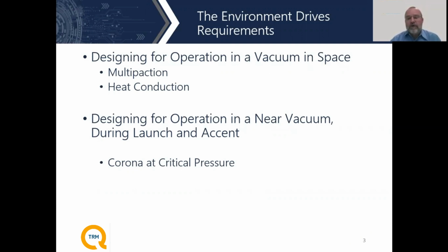Another thing that's also very important to bring up is heat. When we're designing parts for spacecraft, you have to realize that heat cannot radiate because there's nothing to radiate to. Therefore, all heat and thermal buildup must be conducted away from the components for thermal management.